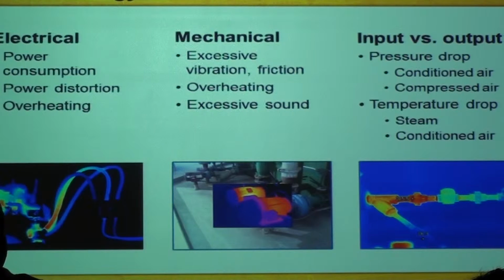What's changing? Again, I squared R. What is changing? Resistance. Resistance changes, current increases, power increases, and that's a sign of heat, and that's why the thermal camera picks it up. But also if you follow that cable all the way, you can see that that particular cable is slightly warmer than the other 2 anyways. And that's telling me, okay, there's probably more load that's flowing in this cable.